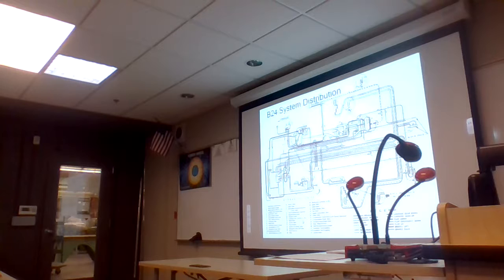As a matter of fact, I think they only have one engine-driven hydraulic pump in the aircraft. And if you read the starting sequence for the B-24, they have to start engine number 3 first, if I remember right. And the reason that they do that is because the hydraulic pump that's engine-driven is on engine number 3. So without that started first, they really have no push of hydraulic fluid in order to make the other components work. So that's why number 3 engine is kind of the critical one to start first.